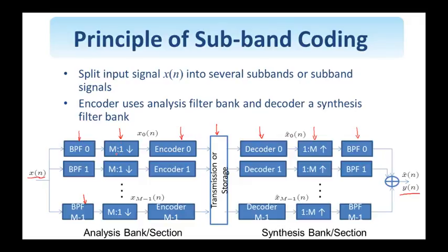We saw what happens if we downsample: the spectra overlap. We have the problem of aliasing. That's why we first low-pass filter or bandpass filter before we downsample, to avoid aliasing. On the other hand, when we upsample, we introduce M-1 zeros in between the samples, and then we use a bandpass filter to extract one replica of the spectrum, because in the frequency domain I have replicas of the spectrum through this introduction of zeros, and through this bandpass filtering, I pull out one replica and I get the signal in the original resolution.